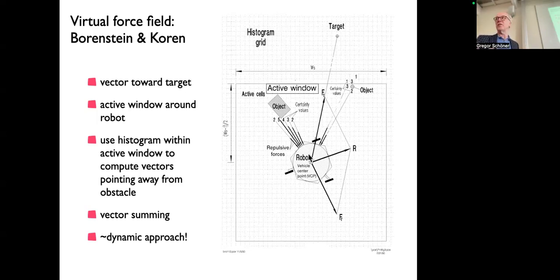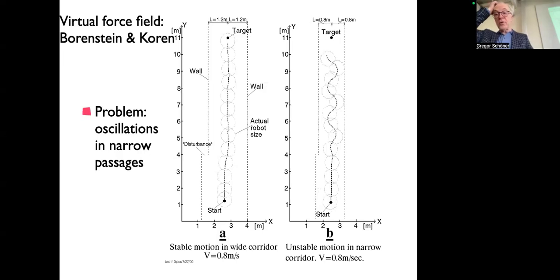And so that is analogous. It's also in velocity space, heading direction space. So they are always sitting in a minimum of this repulsive vector field, right, while they move. And as they move around, it's different parts of the grid that make these vectors. So things change. And again, you have to understand why that really works. This works essentially because the vectors always reflect the world. So it's conceptually like a dynamic systems approach. And that worked, somewhat. They had a couple of demonstrations from one of their papers. It also has this property of oscillating a little bit in a corridor. It's not a big problem.